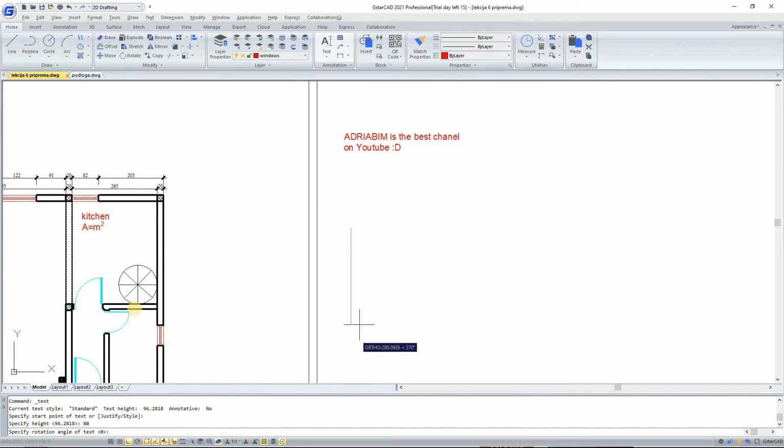And then it asks you to specify the rotation angle of the text. So if you want to rotate the text, this is a very great option. To skip one step, you can also make text by M text and then just rotate it to an angle, but you can do this with single text. So I'm going to say 45 degrees, and I'm going to write